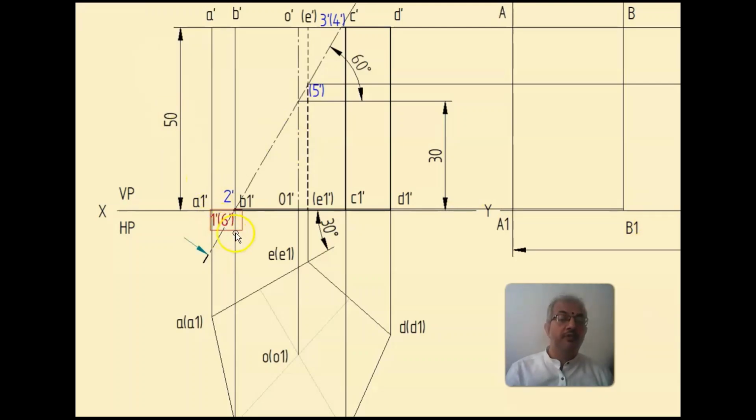In order to represent these points, 1, 6 and 3, 4 on the top face and the base, since the edges joining the corresponding points are not in true length, we need to project these points onto the top view.